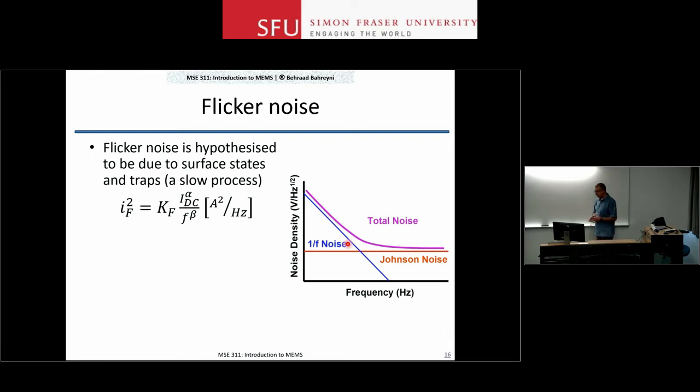So you might say, okay, great, so I only operate at high frequencies. Why would I care about low frequencies? Here's the problem. A lot of the sensing applications are happening at low frequencies, right? So you're dealing with signals that are not too fast. This corner frequency, where you basically have a transition from seeing mostly 1 over f noise to mostly thermal noise, for transistors that you use in electronics is typically around tens of kilohertz to maybe kilohertz range to hundreds of kilohertz range. So it covers a lot of the band that you actually would want to use for sensing.